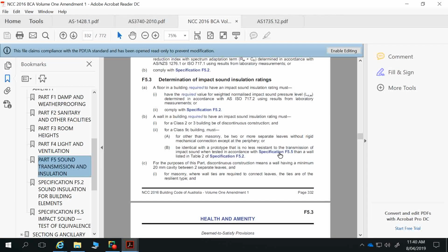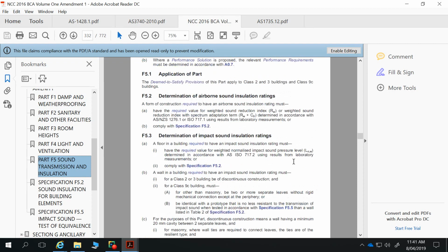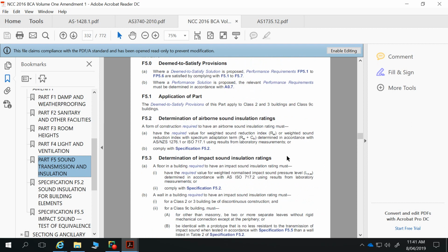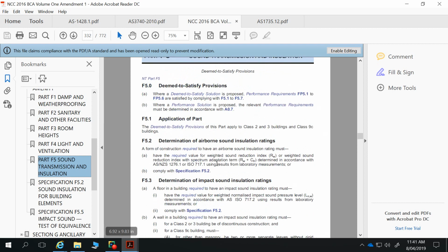For buildings where you do have units above and below each other, you've got to worry about impact sound resistance as well, such as stomping on timber floors and how that travels through, plus the sound insulation between the two, and also wrapping of pipes to ensure that we don't hear people flushing their toilets from upstairs every day. We don't want those sounds carried through the plumbing. But we're not going to have to deal with that with our buildings. We don't have any habitable buildings above or below.